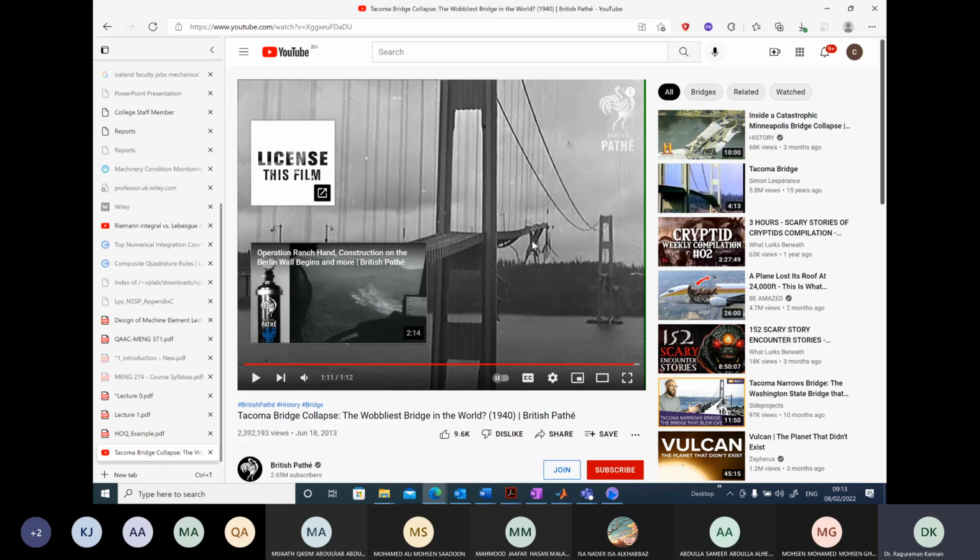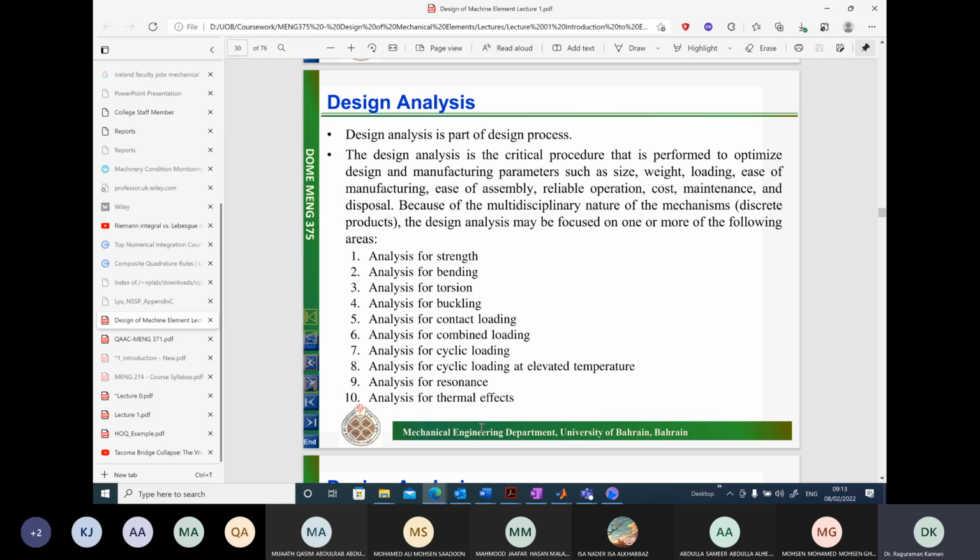This is called resonance frequency, and we will see in the later stages of your course how to calculate the resonance frequency for your shaft. For example, when a shaft is rotating, there are formulas through which we can calculate the resonance frequency of the shaft, and we must avoid operating at those speeds. If you operate at those speeds, it will lead to violent vibration and immediate damage to your particular component. So did you get the conceptual idea of what resonance is?